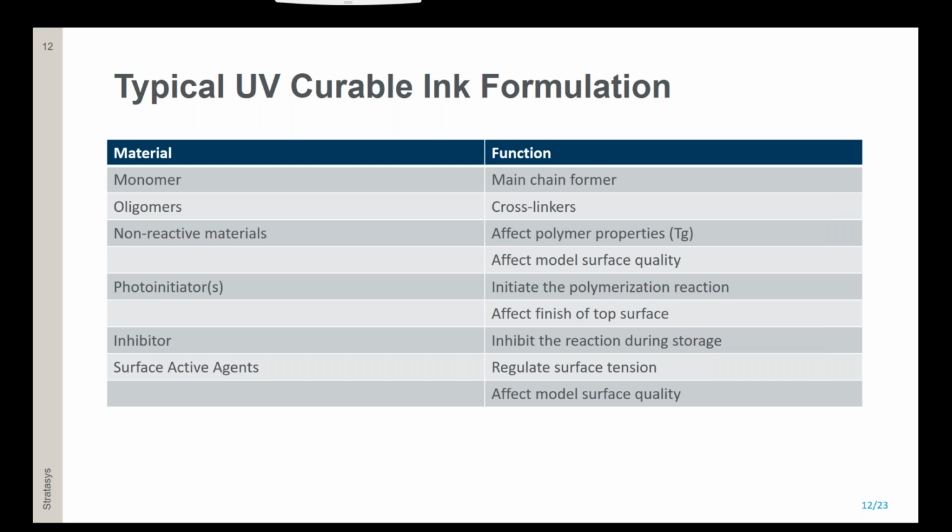So we also have photoinitiators, which, as I said, initiate the polymerization reaction, but they also have an effect on the finish of the top surface. So some photoinitiators leave the surface sticky or not very nice to the touch. So you sometimes need to use other photoinitiators to get a smoother finish, which will be less sticky.